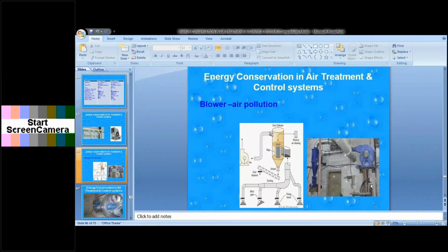So once we redesigned the ducts and the capture velocity, the capture duct was away from the tank. It was trying to draw the air from outside instead of taking it from the exact tank. So we reduced the height of the hood and put it near the place where it has to capture the fumes. Like that we modified. So it eliminated the outside infiltration of air. Additional air, if you take in a centrifugal fan, will draw more power.